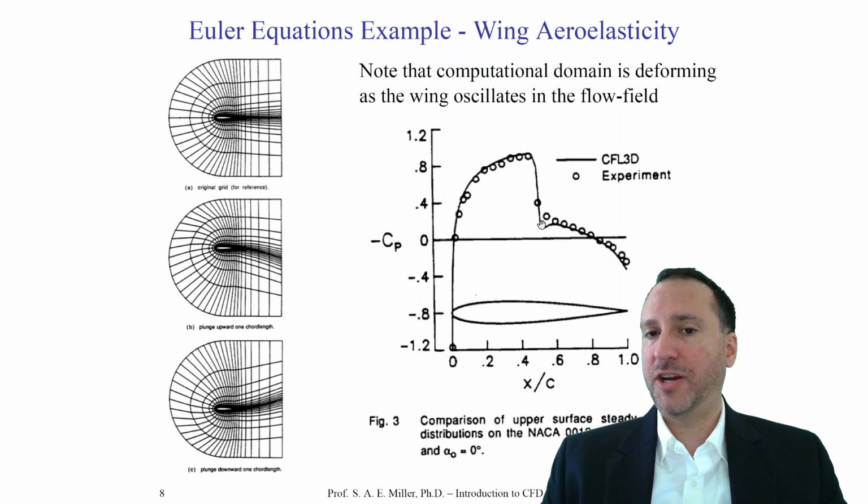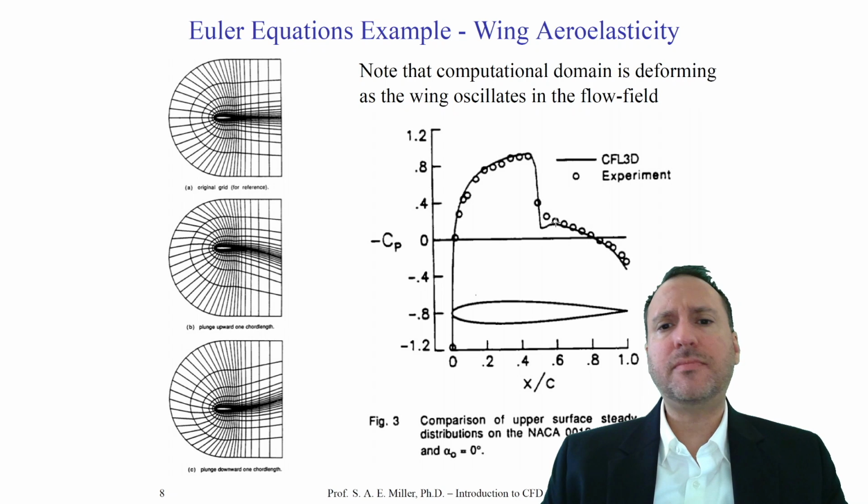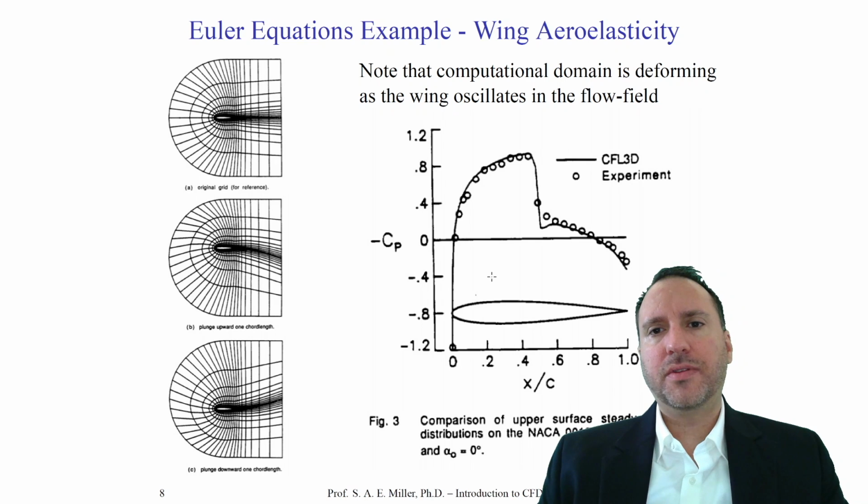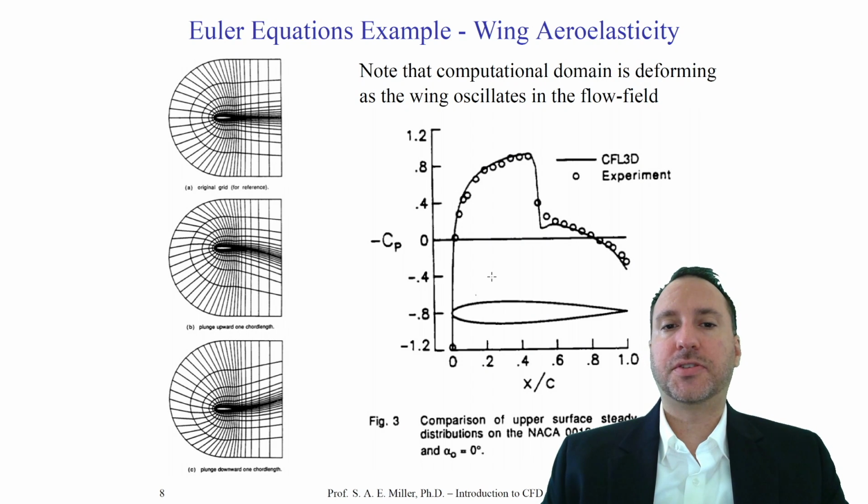And see, this is the pressure increase of the shock from the flow going from left to right. So this result is correct, and the Euler equations have made some good predictions. This is a case where the flow hasn't separated. It's a relatively high-speed subsonic flow, and it's made a good prediction, solving the Euler equations, which are much cheaper than, of course, the full Navier-Stokes equations.